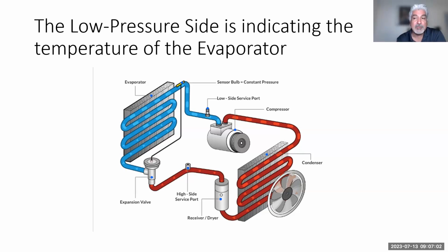And I've seen cases where guys say, hey, I got something wrong with the refrigeration, it's still blowing warm or lukewarm. And in this case, it has nothing to do with this refrigeration system you see here on the slide. It has to do with the HVAC doors not fully closing. In other words, the low temperature door, as I like to call it.